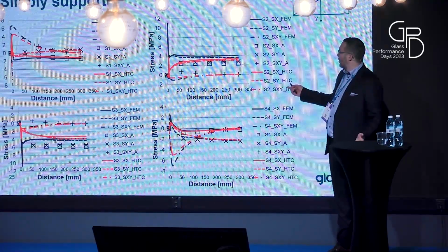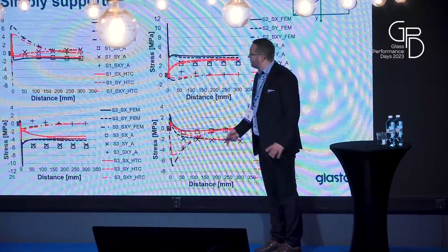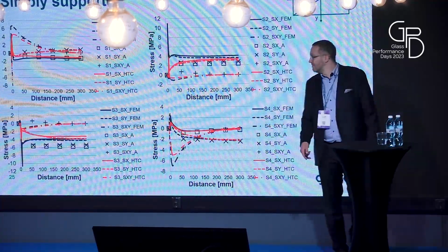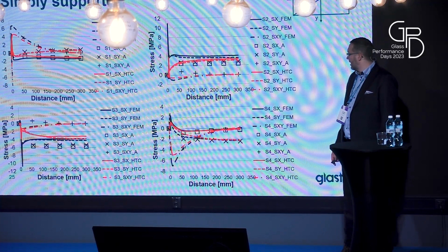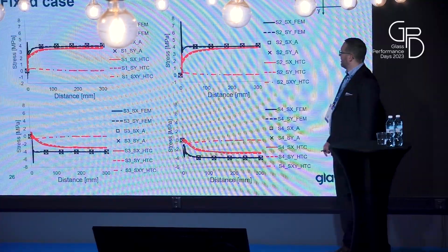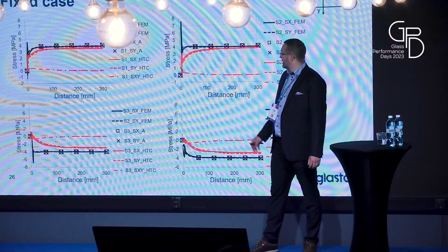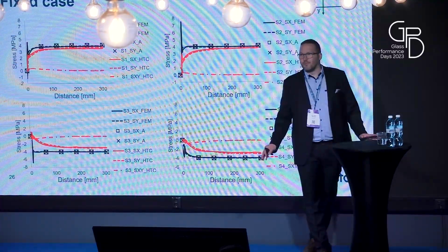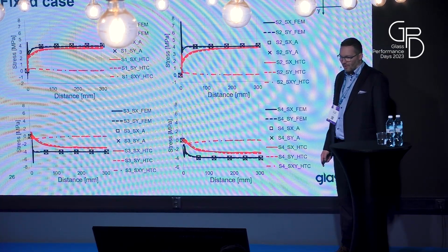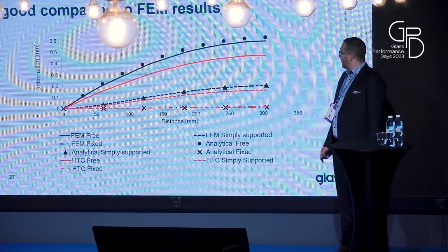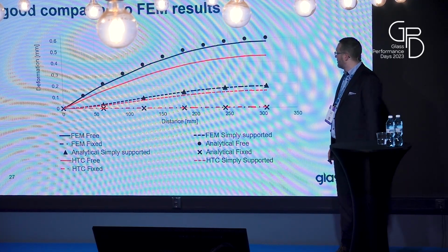If we go to simply supported, same thing again. There are some slight changes, say in shear stress, say for free and fixed case, but like in here, you can see that in the uniform temperature case, shear stresses were 0, but now we get small shear stresses in this non-uniform temperature profile. And the bending is now less because the temperature difference is smaller.